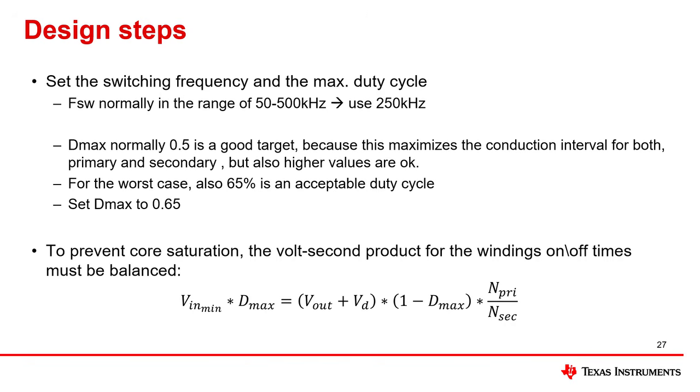To prevent core saturation, the volt-second product for the on and off times must be balanced.